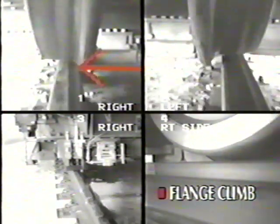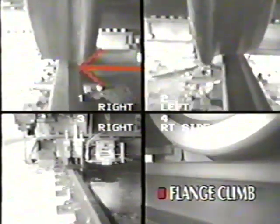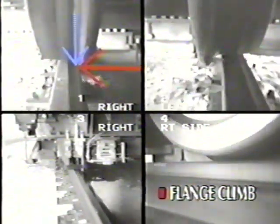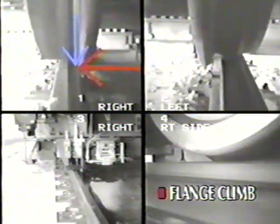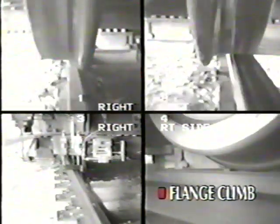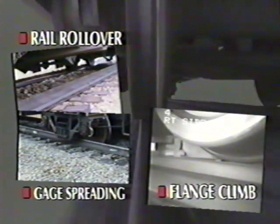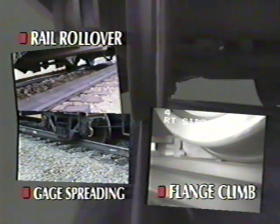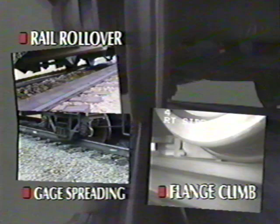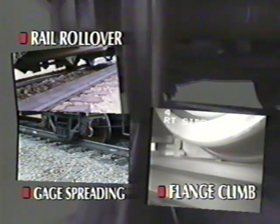The potential for flange climb derailment increases when a rail car wheel generates a force against the gauge face of the rail greater than the load carried by that wheel. Under these conditions, the wheel may climb up the gauge face of the rail and derail. To better understand the forces involved, it is important to distinguish between these two types of derailment scenarios. Each involves different interactions between the rail car and track.